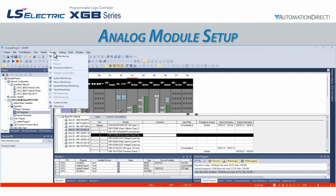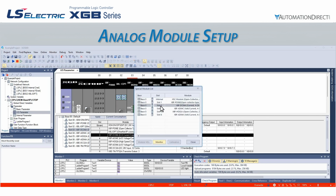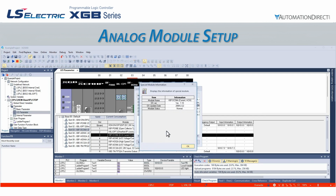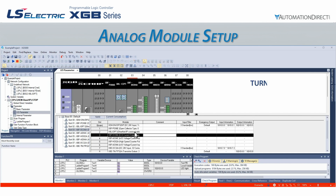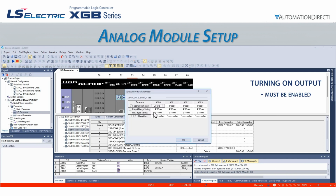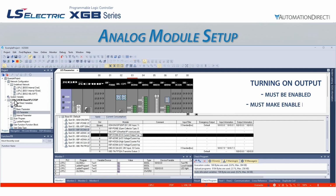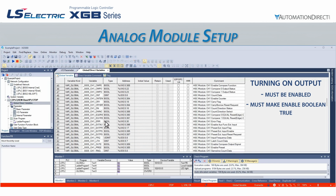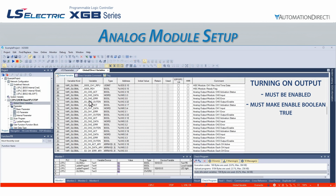Seeing real-time data and testing these output channels in stop mode uses the same special module monitor screen we used for the analog input module. The module information screen is also available for analog output modules. Finally, to control these output channels, they must be enabled in the operation channel settings. Once enabled, the programmer can use the software-created Boolean global variable for the channel enable to actually turn on the output. These auto-generated variables can be found in the Global Variables tab of the Global/Direct Variables screen.